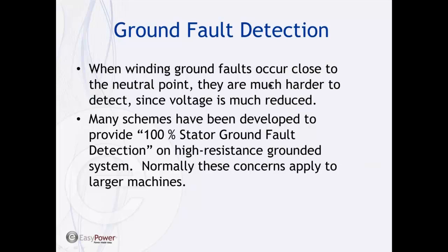But I'm not going to get into all the details of all the different approaches that have been taken, but just be aware that there will be a limit. If I'm just using my normal high resistance grounding and voltage detection, there will be a limit. You might only get 90% of the stator winding for ground fault protection. You got to think about the part that you're not really going to be able to detect. But there are schemes that try to do that.